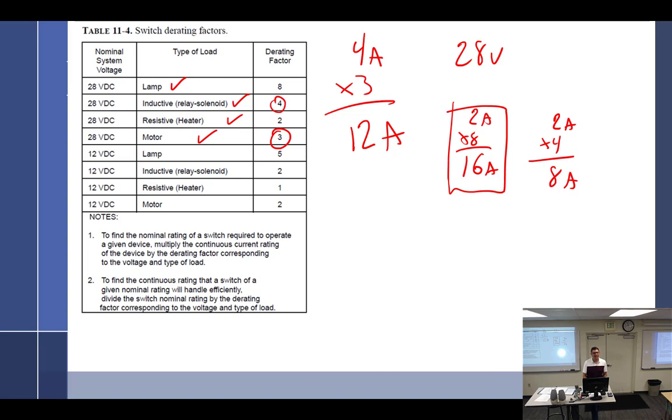It's going to depend. The way I would do that is I would find the switch, what it looks like, how big it is, how much room I have, and if it doesn't make sense, then I'm going relay. So you kind of do it almost aesthetically, by how you feel.